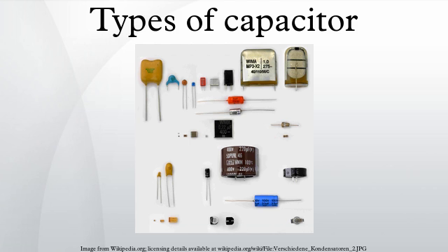In principle, any dielectric could be used to build Class X and Class Y capacitors, perhaps by including an internal fuse to improve safety. In practice, capacitors that meet Class X and Class Y specifications are typically ceramic RFI/EMI suppression capacitors or plastic film RFI/EMI suppression capacitors.